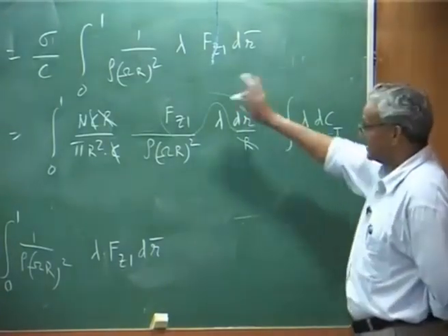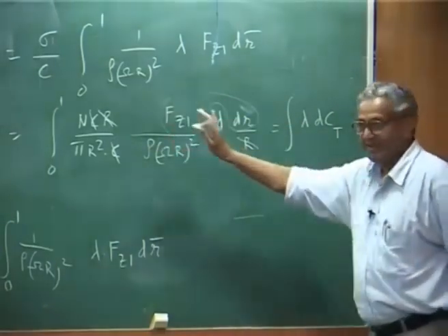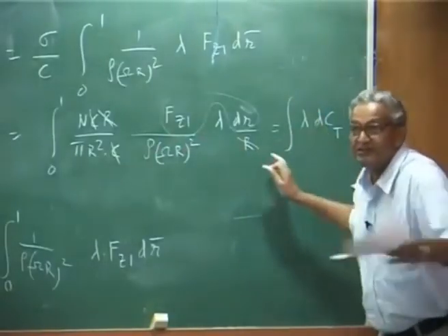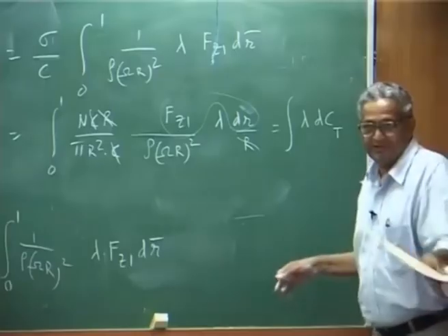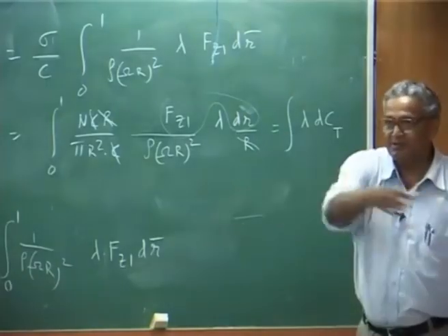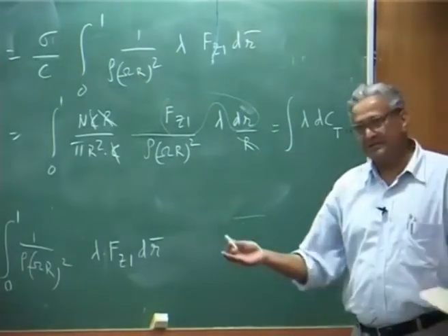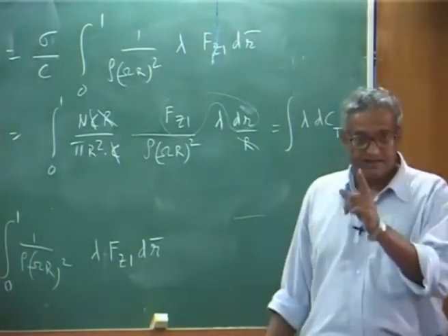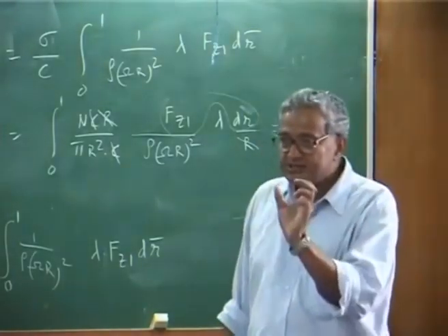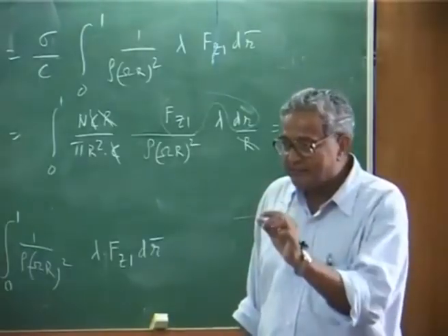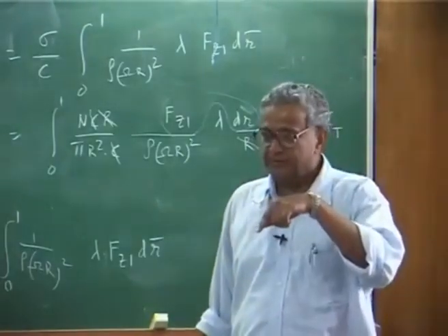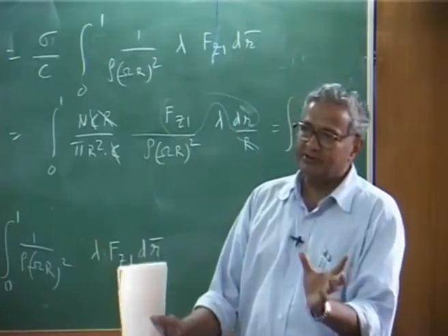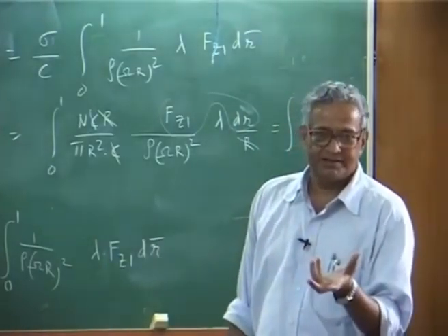That is why that averaging is always included, over the full disk, 1 over 2 pi, it is always there. So, dCT, because we mentioned earlier CT at every time is varying, but when you do the averaging you get the mean value of the thrust, okay.